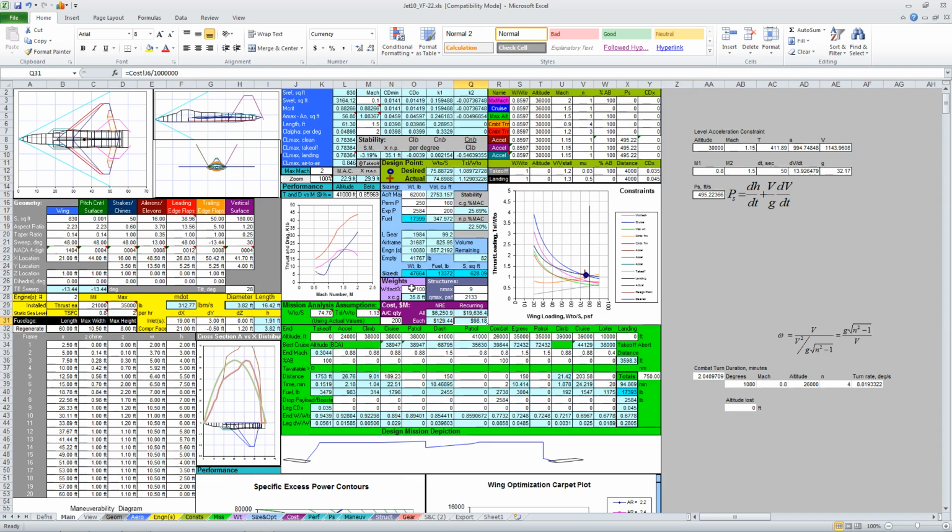One of the things we notice is that this wing has a fairly high taper ratio. Now, if the wing sweep was less than 45 degrees, we would have a rule that says the taper ratio can't be below 0.23. And that's because when you have less than 45 degrees of sweep, you really don't get leading edge vortices, and so you'll experience tip stall.